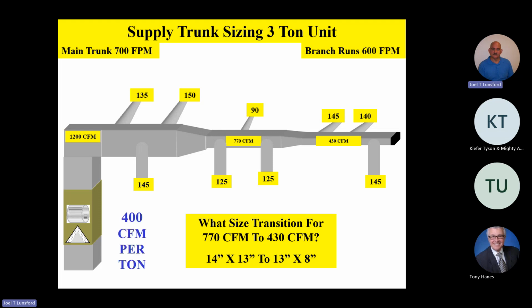Everything else is secondary. You know, if your line set was a little bit long, you can work around that, and so on and so on. But if you get the airflow right and you keep the system clean and dry, those are the two top things that you're going to have to build in reliability and comfort for your homeowner.